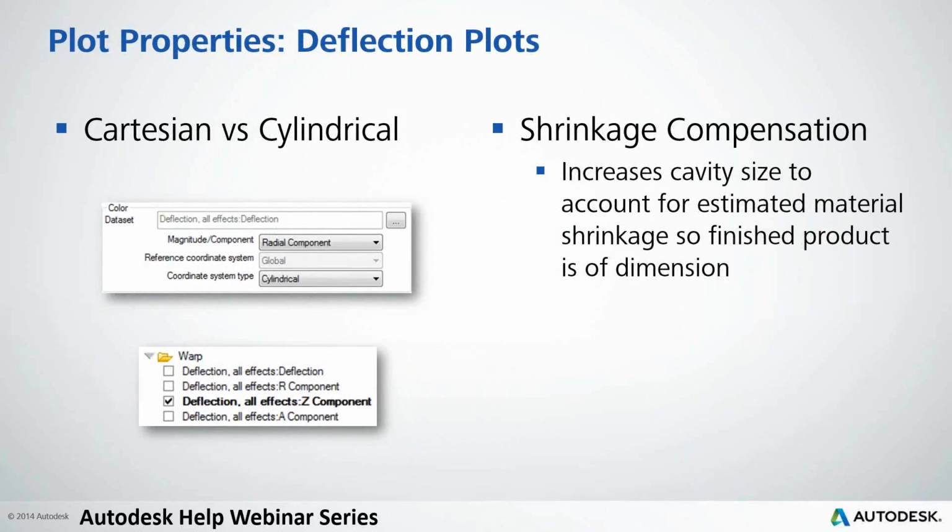there's a second place where you can actually customize these deflection plots. And this is actually located in the plot properties. So again, once you have that result enabled or visible on your screen, then you would be able to go into those plot properties for that result and switch over to the deflection plots tab. And there you can see a few more options to customize it.